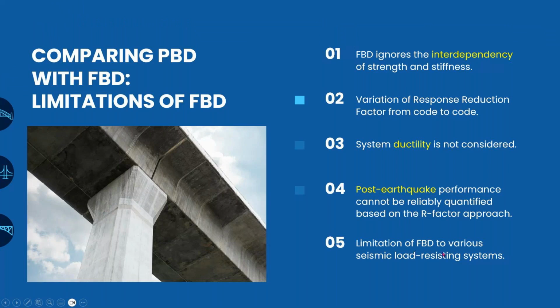Then the limitation of FBD to the various seismic load resisting systems. We know that there is always research going on, and new load resisting systems, such as different types of damper systems or base isolation systems, come into the picture every day. And these systems are not tested in past earthquakes, and thus the prediction of the performance of these systems is not possible by using the force-based design approach.